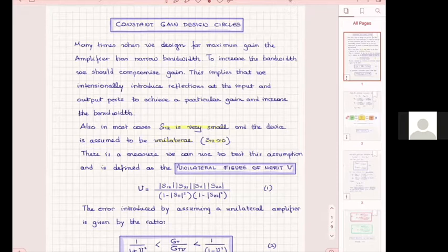Now, we talked last time and we said, in general though, having that in mind, after you have selected the operating point, both in bias and in frequency, and whatever other aspects of design in your amplifier, the next and the most important thing in controlling the bandwidth of your amplifier is your matching network.